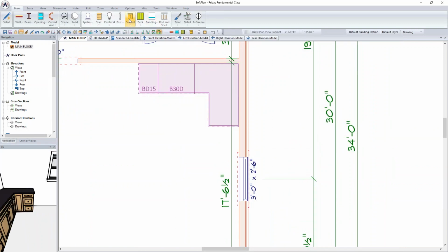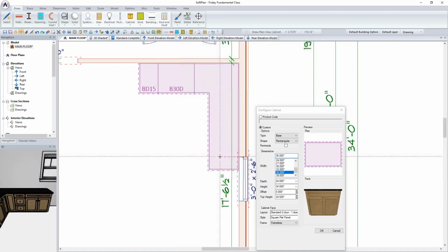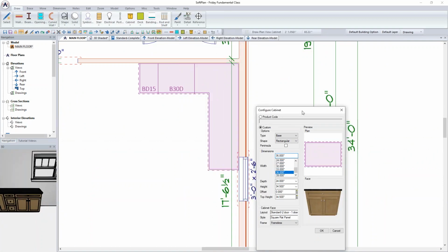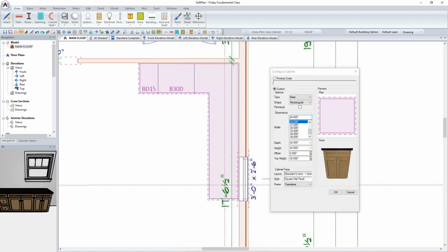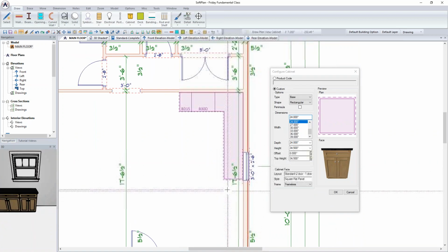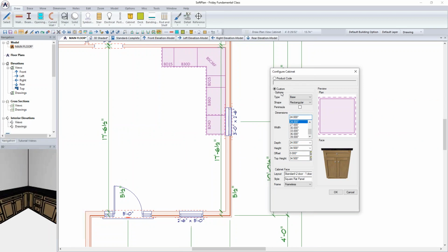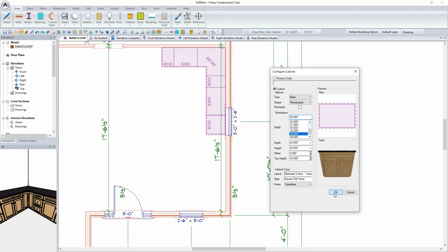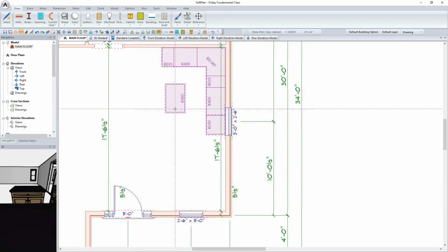And now I could pick the drawer select, and I could pick that same 15-inch cabinet to draw it there. All right, and so as I return back to the dialog, 36-inch, drawer and door, because we're going to place a sink in there, and then a 24-inch, and so we've got somewhere to place a dishwasher and so on. You could literally draw each of these out on the actual plan itself. Now, once I've done this, and if I wanted to draw something like an island very quickly, all right, you could literally just click to add one of these in here.